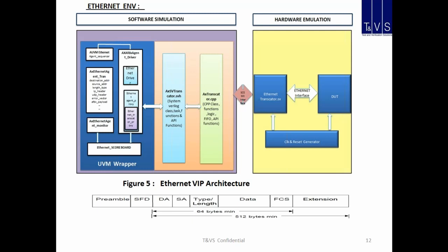Yeah. I mean, from this picture, it's not very clear. You might have multiple interfaces. Yeah, I think this is one just for a block level verification. But that on the right-hand side could easily be an SoC, and you could have multiple transactors. Just to add one thing, it's not only one SCE-MI pipe when you go at the system level. You can have as many SCE-MI pipes, as many transactors as you want at the system level. And emulation is the best solution when you do performance testing or when you want to verify SOC.